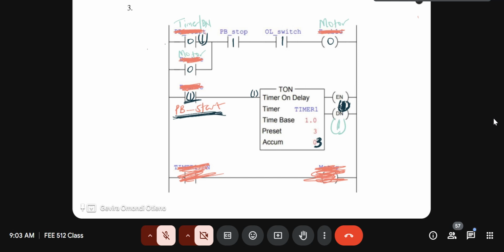So I'm actually concerned, because I'm thinking having the enable bit and the done bit connected to the output rail might also be a problem for run 2, because that will mean that the timer will have timer reset issues. It might reset even when the preset value has not already been reached. I don't know if you can say something about that.